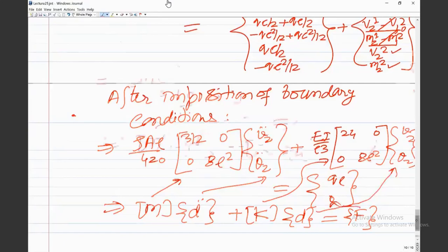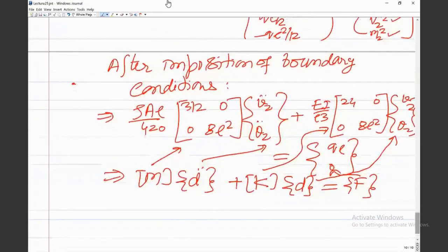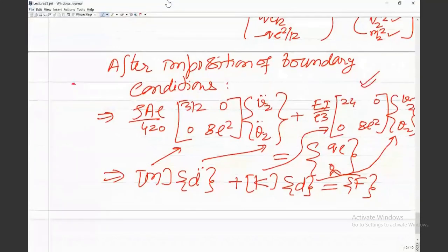So like that we can derive these. I want to stop here, and I will continue with a few more elements. Subsequently I will discuss how to get the mass matrix for other elements, but this is how the entire assembly, the imposition of boundary conditions, and the final equation of motion work. So this is the final equation of motion you get. I want to stop here, and if you have any doubts and questions, you can ask.